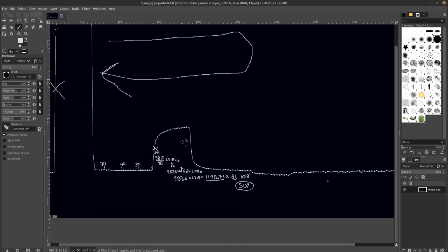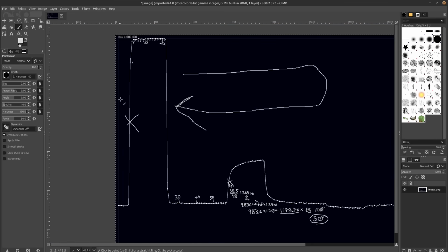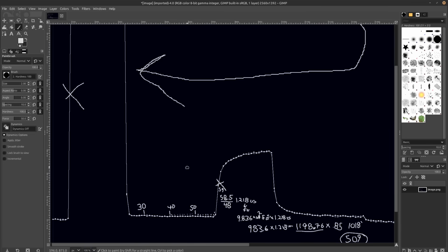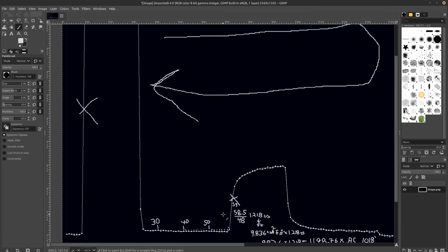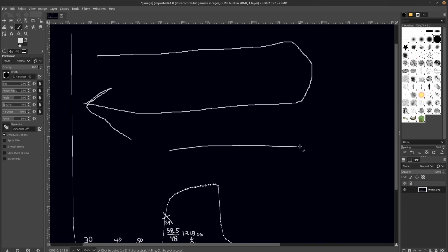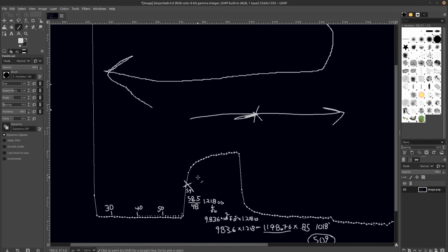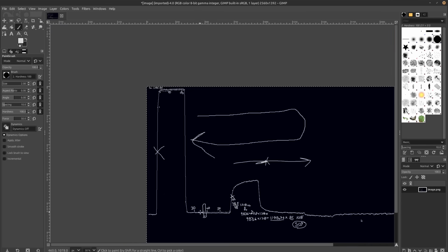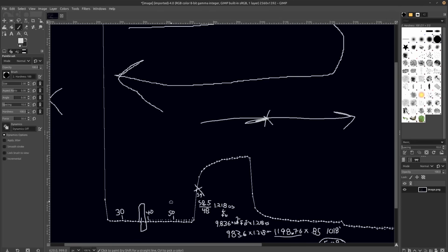This is kind of a toy problem right here that we did with just a cable going here and back and then seeing that it wasn't terminated right. But this is used in real life for things to try to identify where in a cable there's a problem. So if you have like a long line, like back in the days of DSL, and there was a problem, like a cut in the cable or a short to ground, you would actually see these reflections going in at different points in the cable. And by doing this, you would be able to identify where in the cable there was a break.